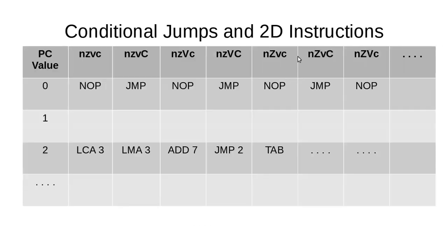Let's assume that we have a 0 flag value. We'll do nothing. We'll move to program counter 1. Let's assume that we load the number 5 into the B register. Well, we will go down to PC value 2, but loading the value 5 into the B register won't be an ALU operation, and so therefore we'll stay in this column because the flags value will still be 0.